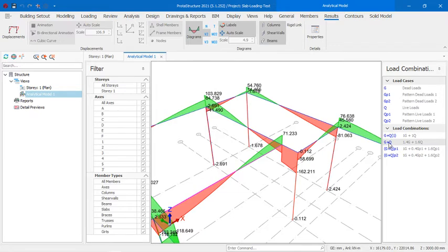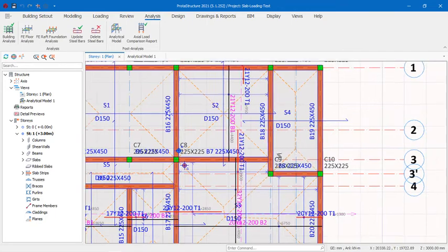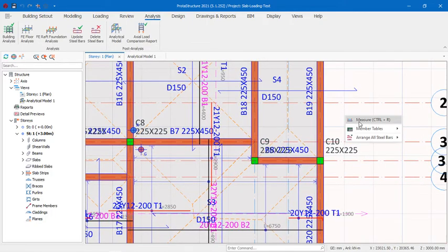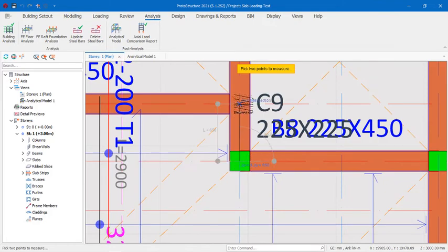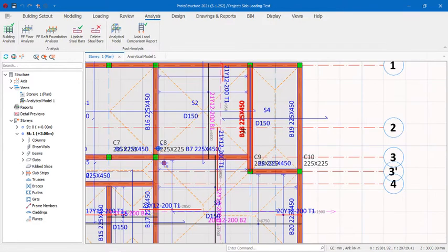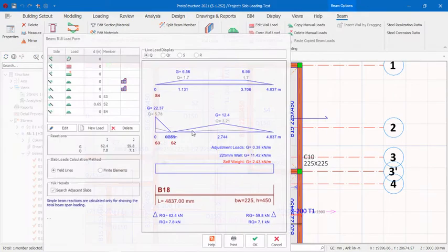That is all load has been factored. You can see the load combination. So it's 71.23. Now let me define this 71.23 on that beam. Don't forget 650 is the distance. Measure distance 650. So I will now come to this beam and say edit member load like before, and I